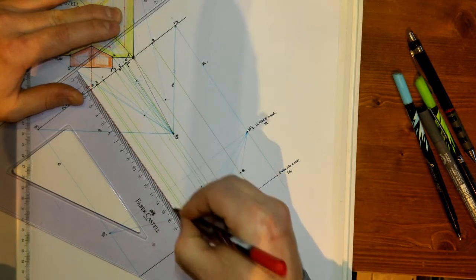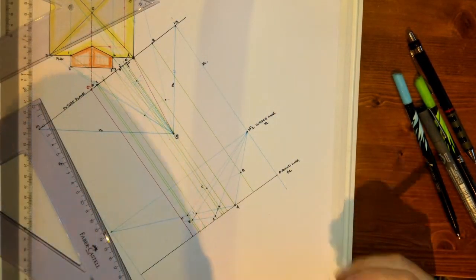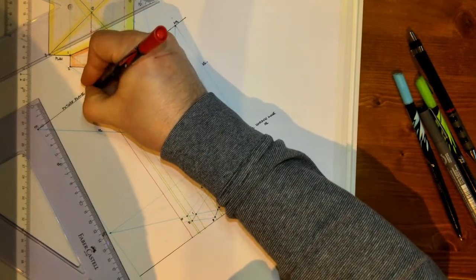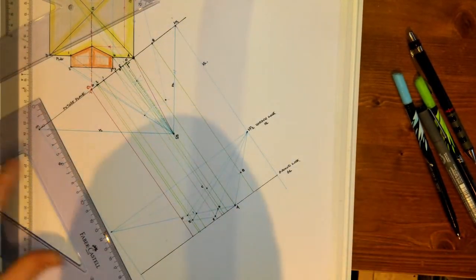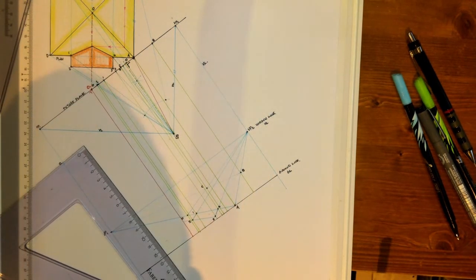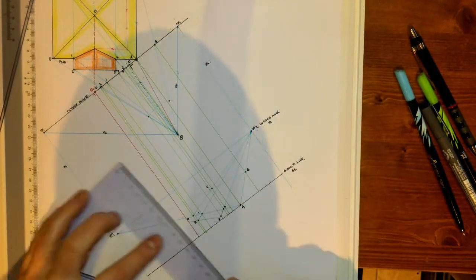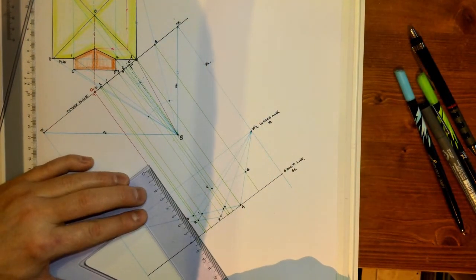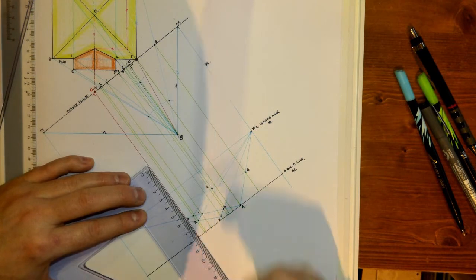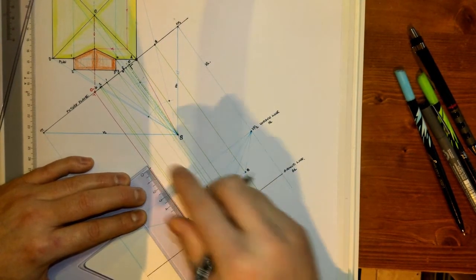I'll bring it down as just a solid red line, like so. Okay? Now, I have that line brought down. It's at a right angle there. And what I'm going to do on this line, because now we have virtually, if you want to call it, moved the point O down onto the picture plane, we can actually mark a true height on this line now. So the true height for O in the original drawing is 80. So from the ground line, I mark up 80 millimeters.